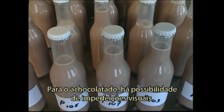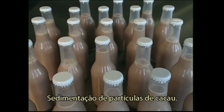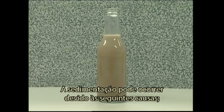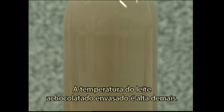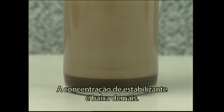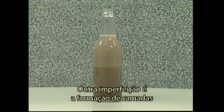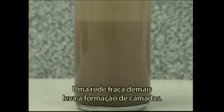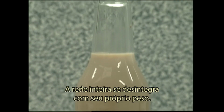For chocolate milk, there are some potential defects in the appearance. Sedimentation of cocoa particles. Sedimentation can be due to the following causes. The cocoa powder is not fine enough, the temperature of the chocolate milk bottled is too high, the concentration of stabilizer is too low. Another defect is layer formation. A too weak network causes layer formation. The entire network collapses under its own weight.